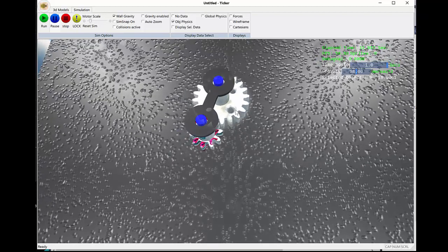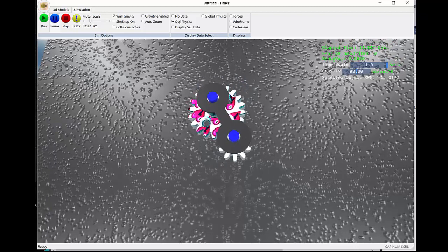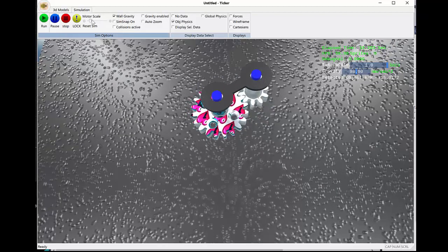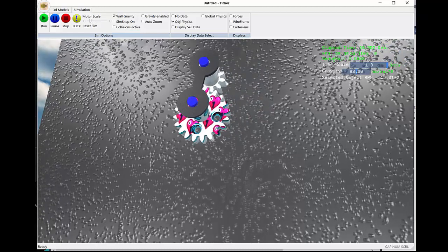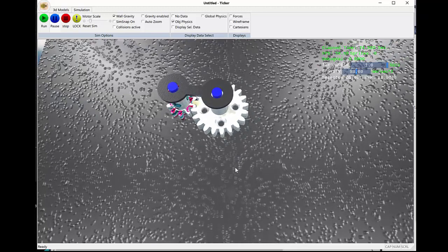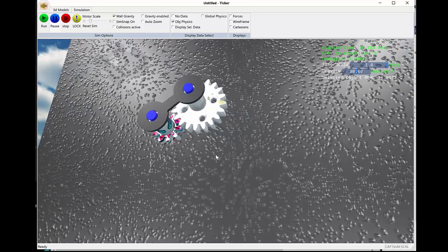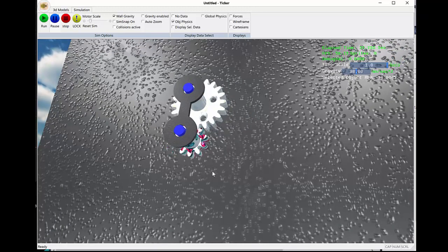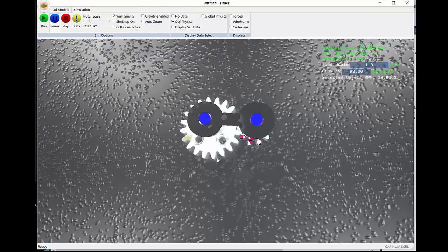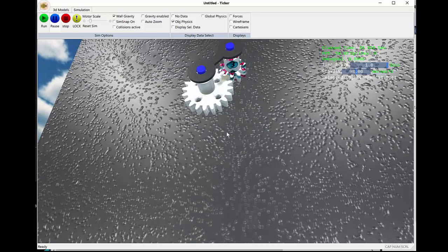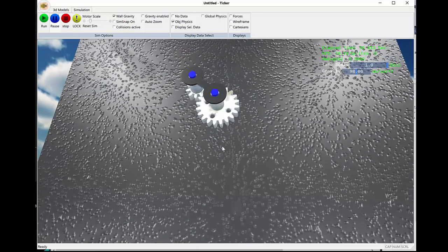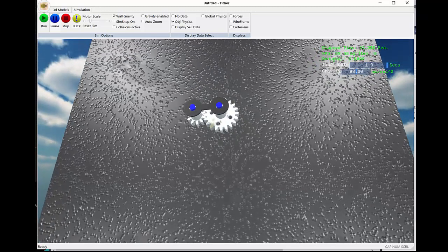This definitely affects RPM. As we can see looking at our RPM for the first motor, which is now at 15 because we've moved to motor scale. If we now look at the second motor, it is 18 RPM. A definite difference from the 2-to-1 normal that you would see. But this is because the second gear is now going around the first gear. So the lesson here is don't necessarily rely on RPMs to try to figure out what your ratio is going to be if you're playing with a piece of kinetic art.